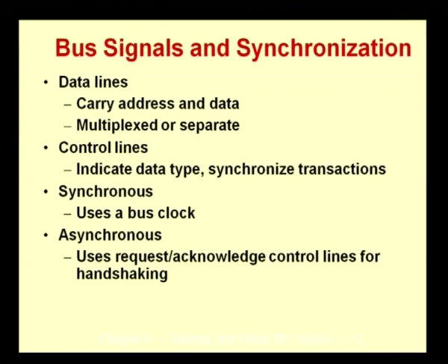So, when we talk of handshaking, it is normally used in the context of an asynchronous transfer, and it is similar to the handshake that we normally do, right, that one person puts out the hand and then another person puts out the hand in response to that. So, you can look at the same thing happening here. One device puts out a request and the other device responds by giving an acknowledgement. So, request and acknowledgement is like doing a handshake, which is why it is normally referred to as a handshake set of operations or handshake signals.